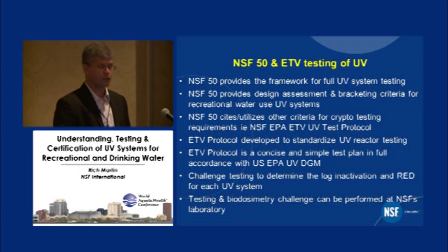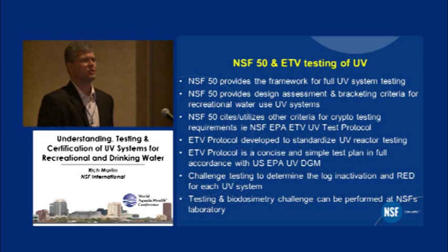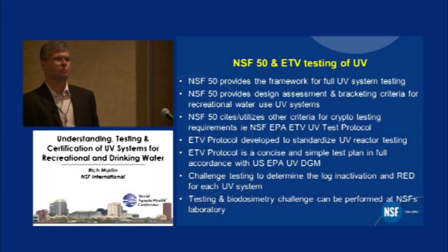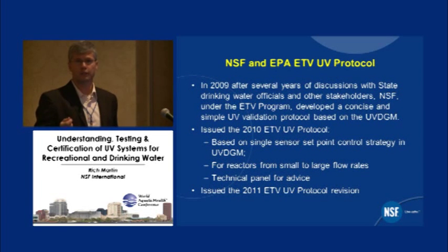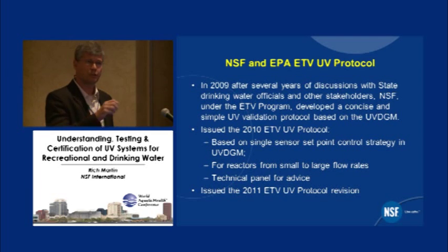and the ETV protocol, and how it's really designed to take this guidance document, which you're probably familiar with, the US EPA Disinfection Guidance Manual, last published in 2006. So that was used to create a test standard known as the ETV protocol. Again, that document didn't tell you exactly what to do, but it gave some guidance, and it was very helpful for water facility operators that might be trying to find the right size UV system to treat their surface waters or groundwaters.